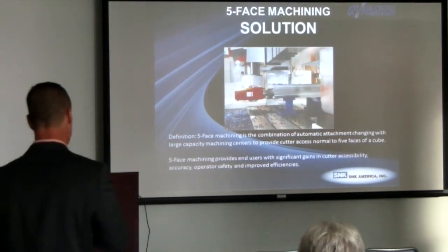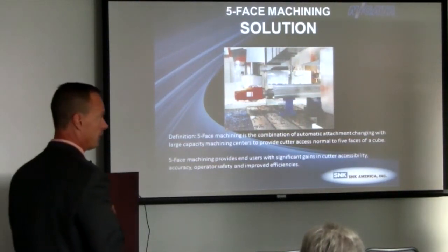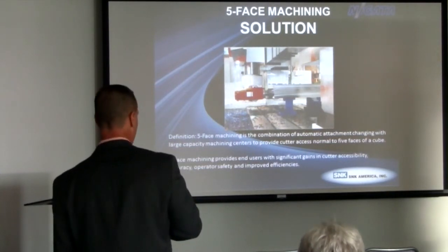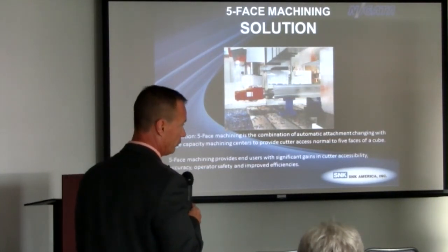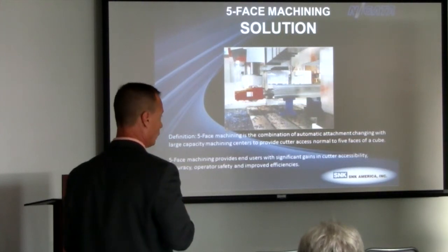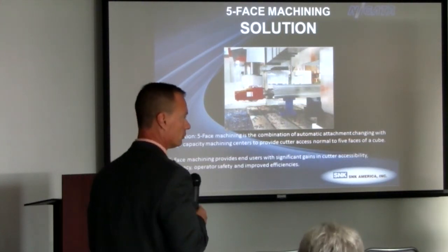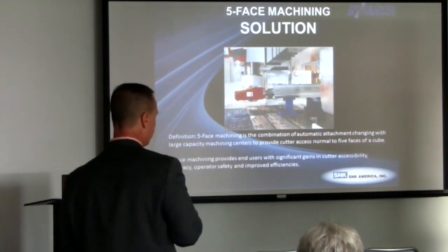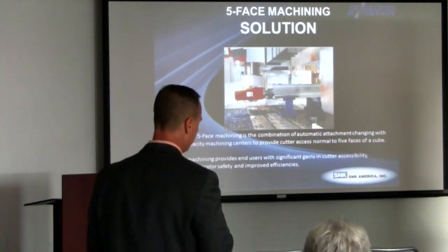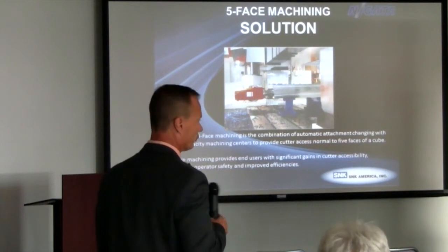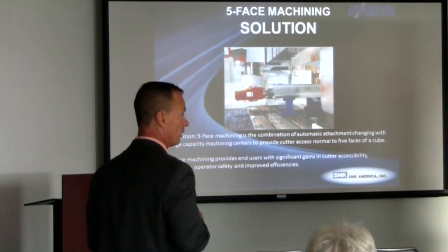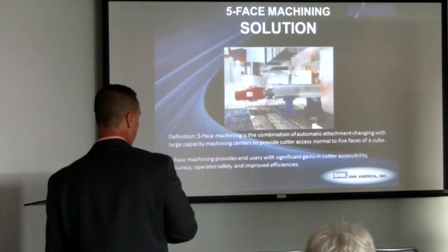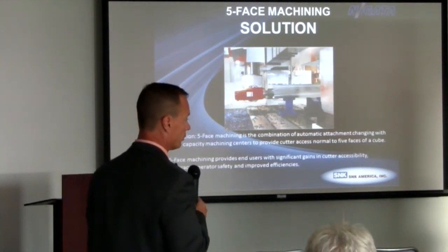What's the benefit to the end user? The benefit is that now you can have a single setup and you can move your tool around the part and gain cutter accessibility to features that you might not be able to reach in a vertical or a boring mill single approach type application. So what we're doing here is we're creating increased accuracy of the part. You're being able to deliver your parts to your customers faster because you're not having a lot of downtime on your spindle as you're flipping or moving the part around. So overall, you're improving the efficiency of your process.